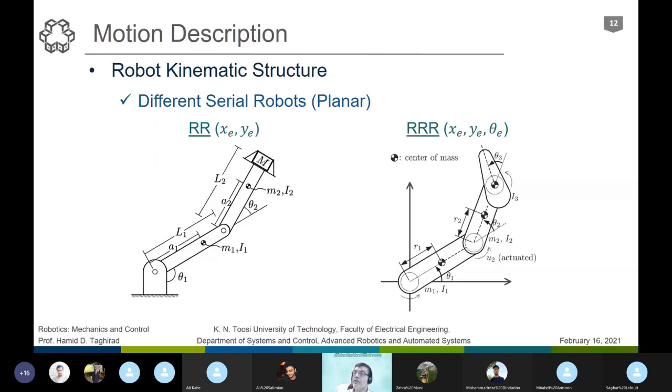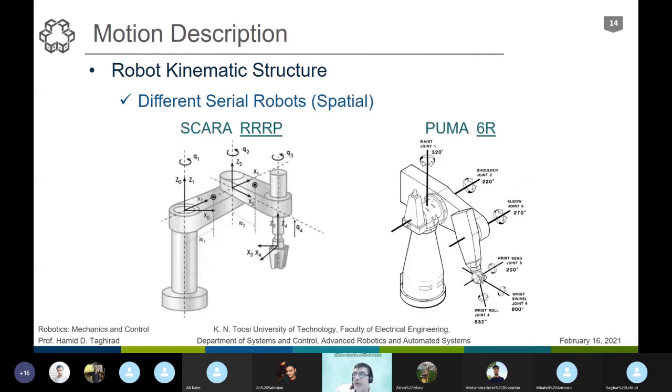So let's also look into 2 other spatial serial robots. The 2 most important ones maybe. The one here is called Scara, which I showed you. This is very, very interesting in terms of pick and place motion, quite fast. It can go to 90 picks per minute. Of course, the closed loop kinematic chain can easily beat this structure and go to 120 picks per minute.